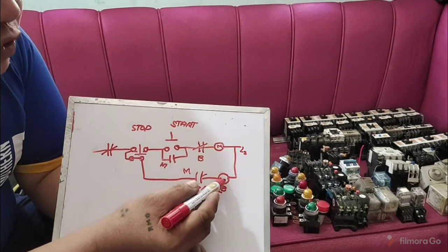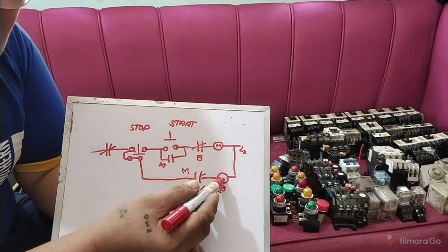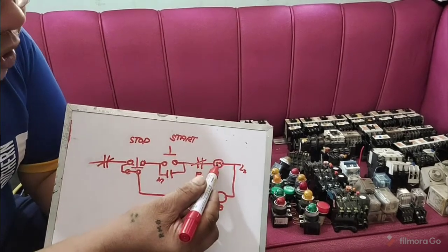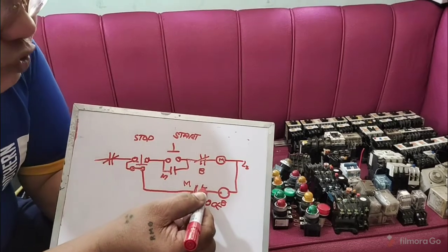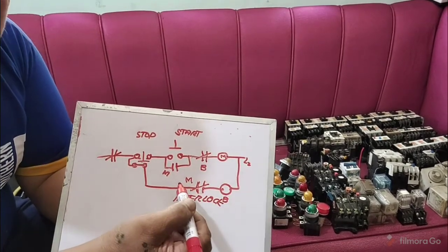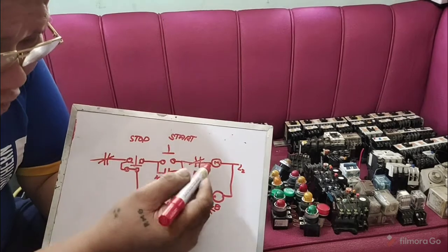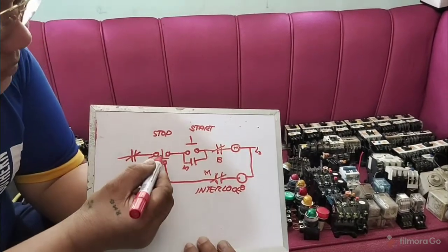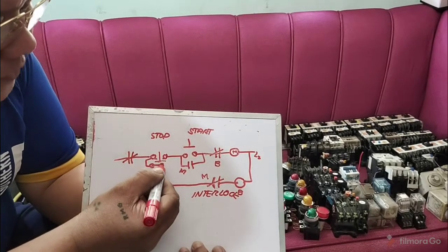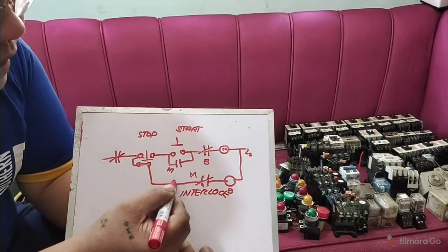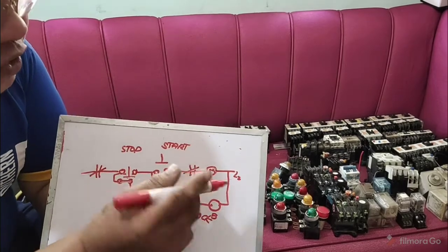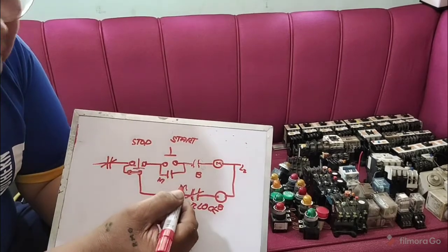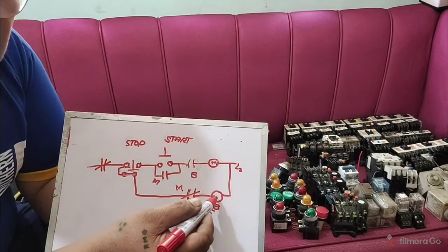Why? Because the brake contactor is still open. You have your interlock here. So you need to turn off the main so that this will go back to its normal position. When you turn off the main, there is an extra rotation. Then that's the time that you will press the stop button. Then what will happen to this? It energizes. So what will happen to the contact above your interlock? It will also open, considering that the brake contactor is energized.